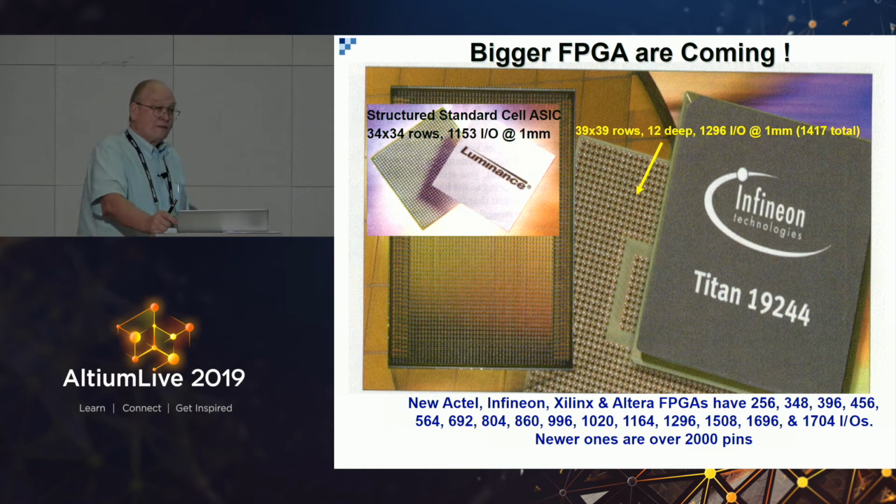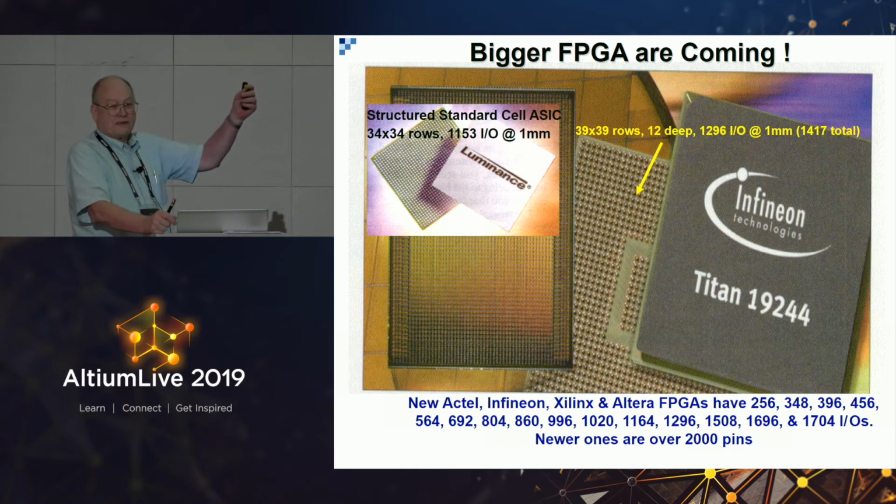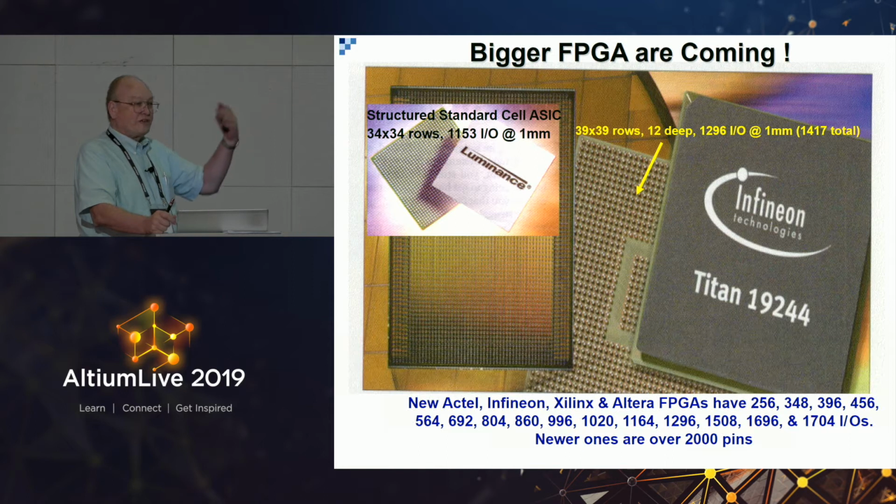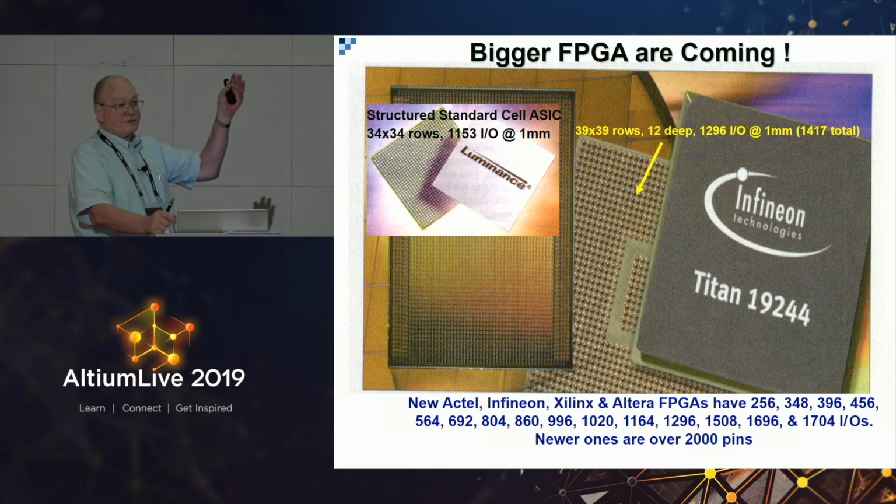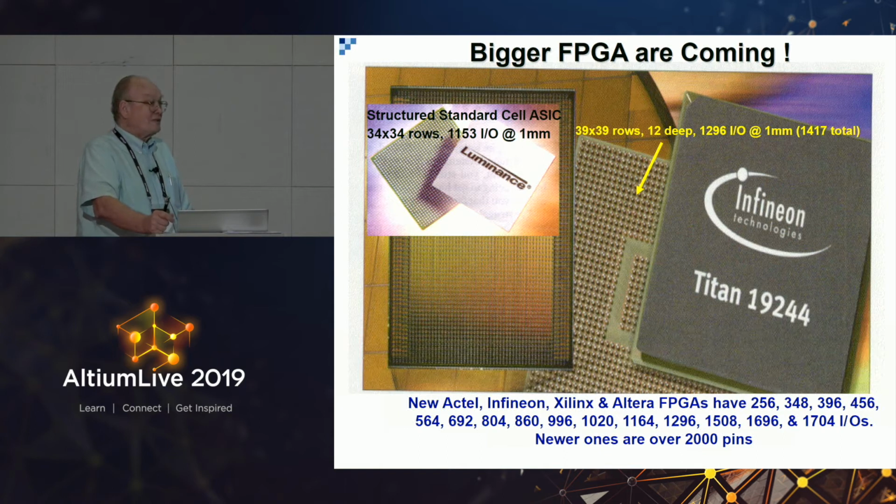In the last session today, I'll go over 3 or 4 excellent case studies in which we took 24-layer high-speed multilayers and using HDI made it 12 layers. Or we took an 18-layer aerospace board and made it 8 layers. Since most of this is not FR4 but low-loss material, going from 18 layers to 8 layers is more than half the cost. The price dropped in half. So anybody that tells you that HDI costs too much, don't listen to them, because they don't know what they're talking about. They're still doing it the wrong way.